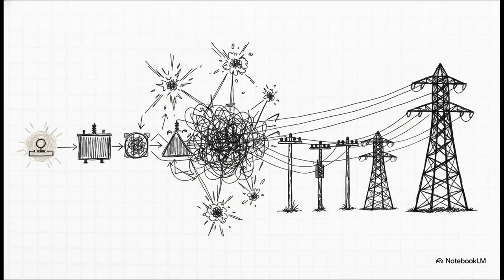To really hammer this home, the text highlights the chaos of a messy single-line diagram. Picture this. You've got an 11 kV generator feeding into 33 kV subtransmission lines, which then step all the way up to 132 kV transmission lines. If you try to run a load flow study using raw ohms and amps across all that, oh man, you'd have to manually track different voltages and completely awkward transformer ratios every single time you cross into a new zone. It just quickly becomes this massive, error-prone mess.